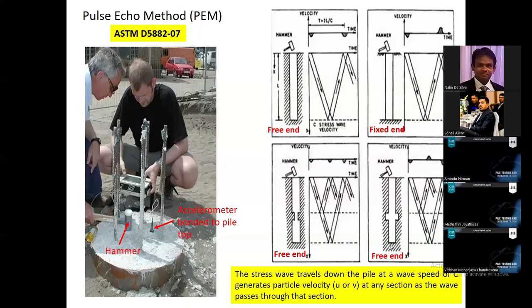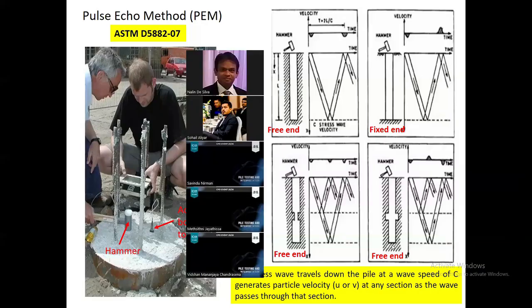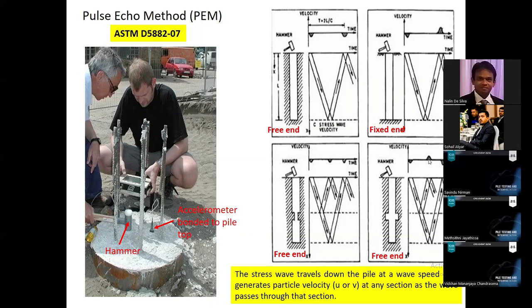Then when the wave goes to the toe, which is free, it means it has a soft condition. So you will see this kind of tensile response, a response similar to the initial wave. So by looking at the direction of the response, we can get an idea about the integrity of piles.